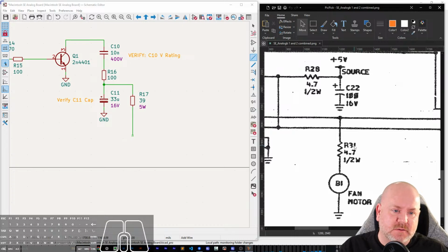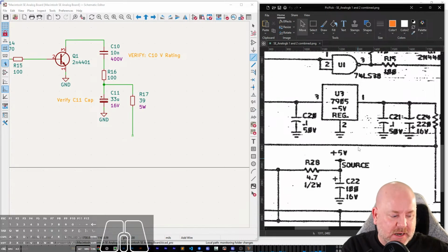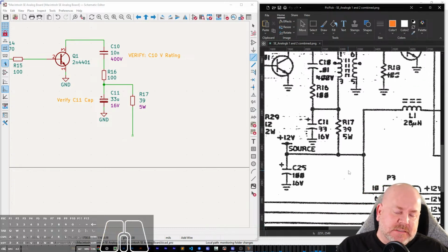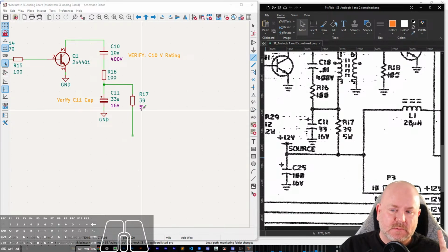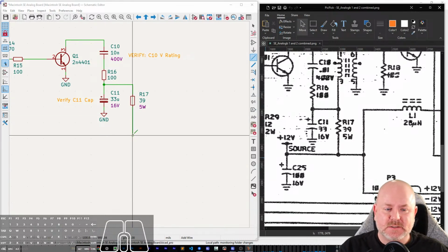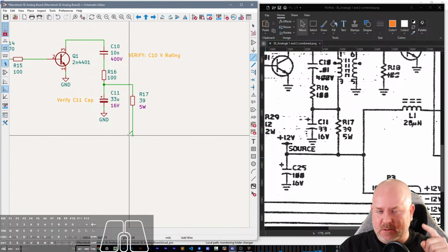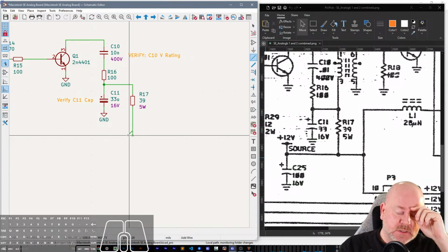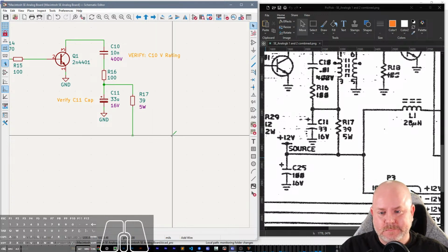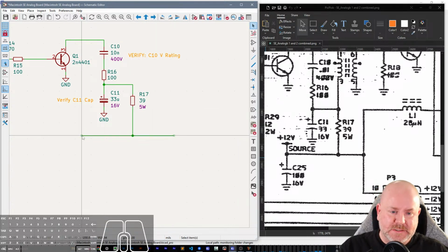Anyway, standards are something a body of people wrote down. A convention is just, this is how we all do it. Another good example is labeling the cathode of a capacitor. I could be wrong, but I'm pretty sure there isn't a standard that says to do that. That's just the convention most people use. That only applies to aluminum electrolytic and aluminum polymer capacitors. Tantalum capacitors mark their anode, not the cathode, for reasons.